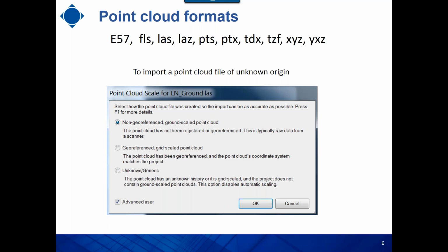These are the considerations that every user of point clouds must pay attention to when bringing them into Trimble Business Center or any other software package, especially with TBC, because it has a survey engine. When we bring in the point cloud and start a TBC project with a template, we need to know what type of coordinate system we're dealing with. If we don't, the point cloud might scale in a way that we cannot understand, and that consideration is very important.